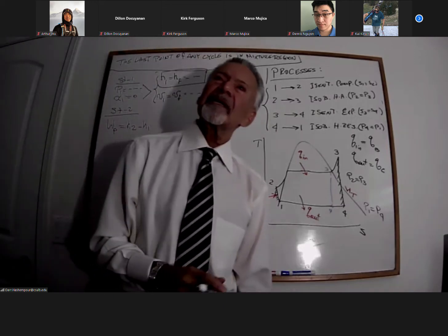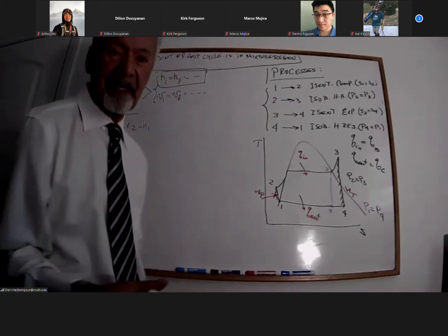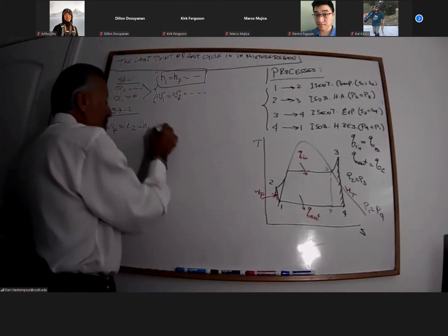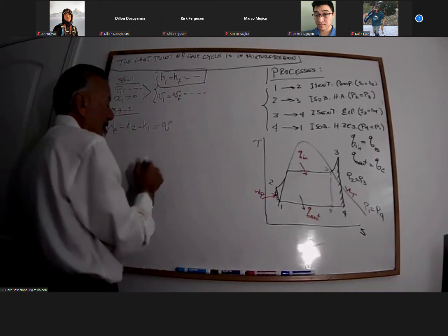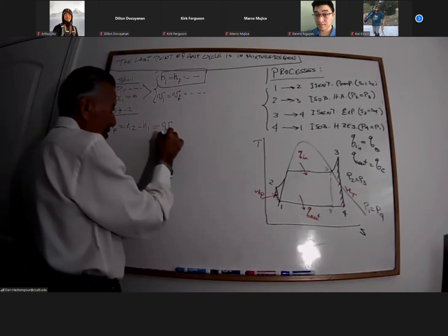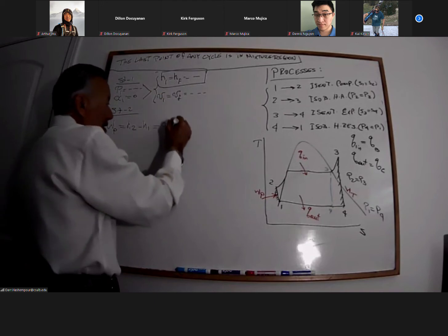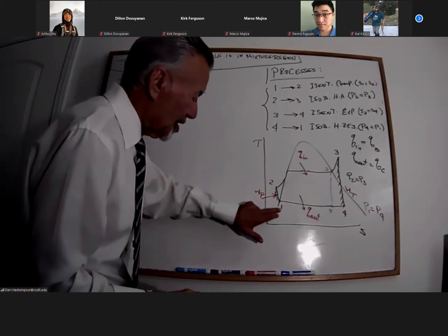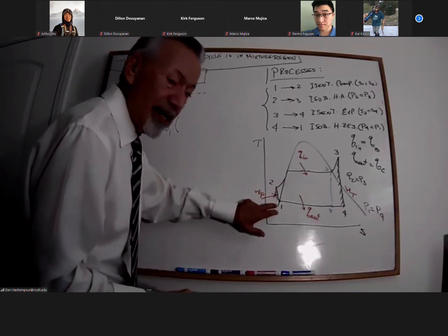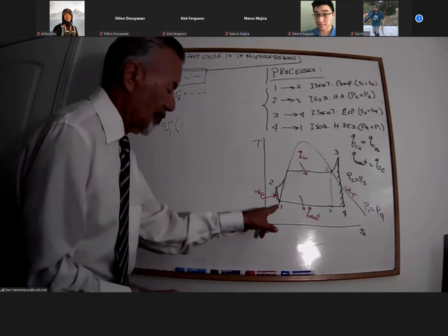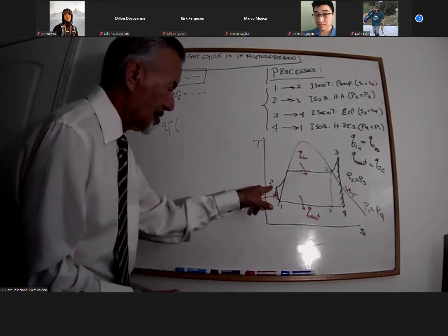I remember how they defined work of a pump. Work of a pump was V, the volume at the base of the pump, which is V1, right there, times the delta P, the pressure between 1 and 2, because I'm taking this water at this pressure to that pressure.